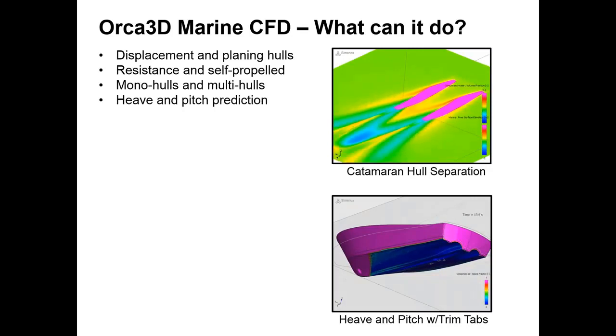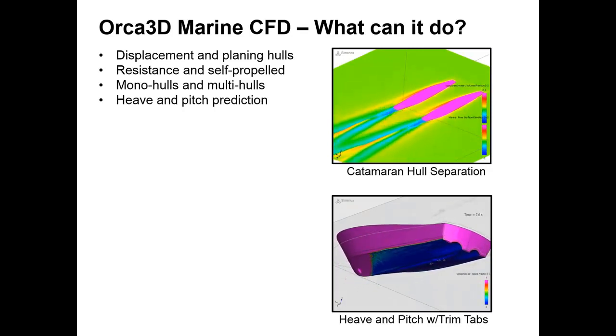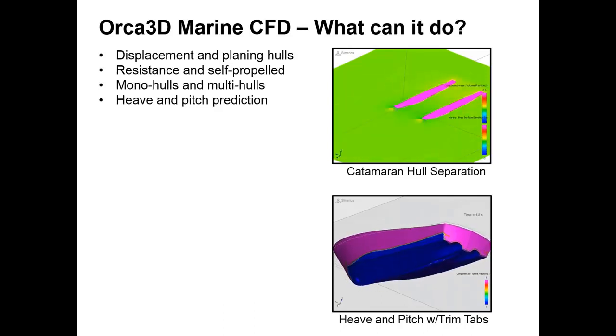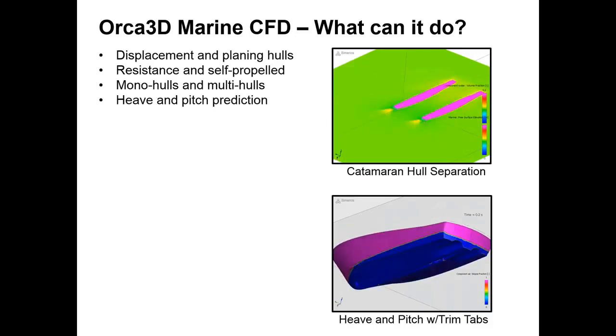You can also perform heave and pitch predictions. In the lower right you see a planing hull that is starting from zero speed and coming up to design speed, and you can see the spray root and how the heave and pitch of the vessel is changing.